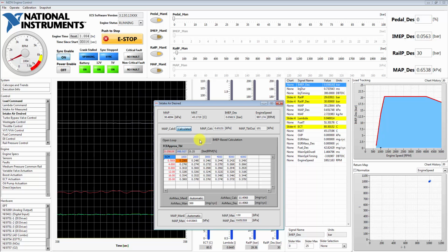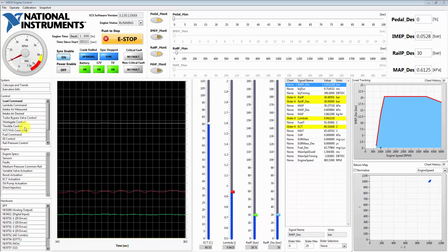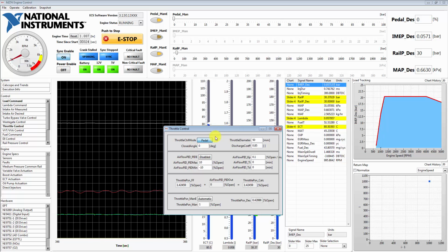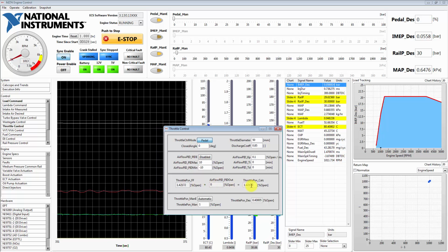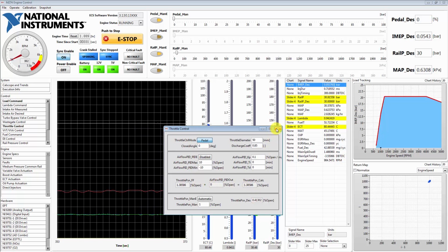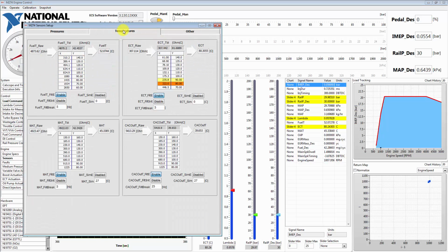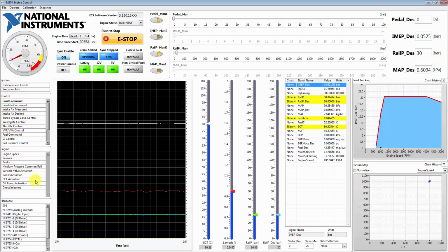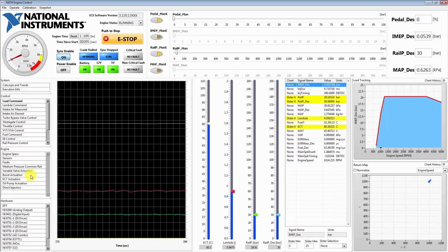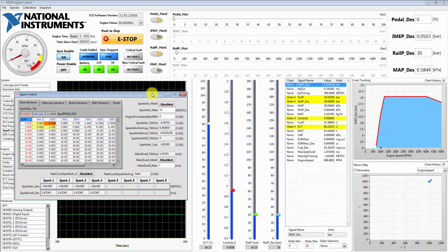Controlling intake air mass flow to a desired set point using a drive-by-wire throttle is a complex task. Often an open-loop lookup table is used for this purpose, or the pedal position is used directly to set the throttle position. The suite of sensors on a given engine is commonly unique to that engine. As a result, sensor calibrations must be known and entered into the sensor's setup in the engine layer. This includes pressure transducer voltage to pressure calibrations and thermistor resistance to temperature calibrations.